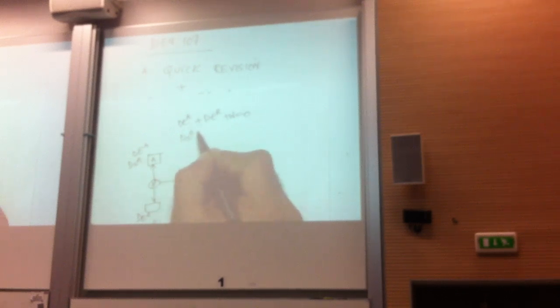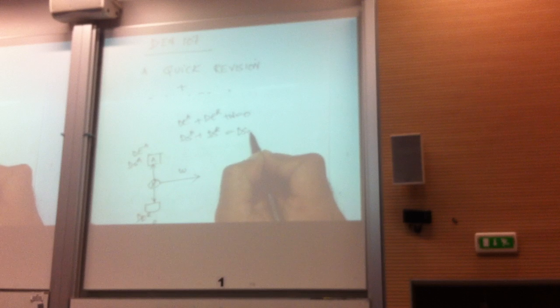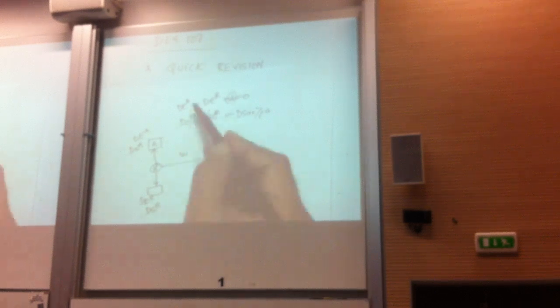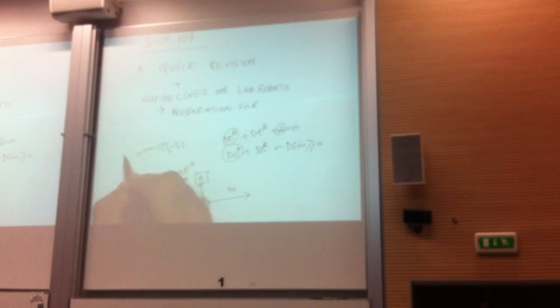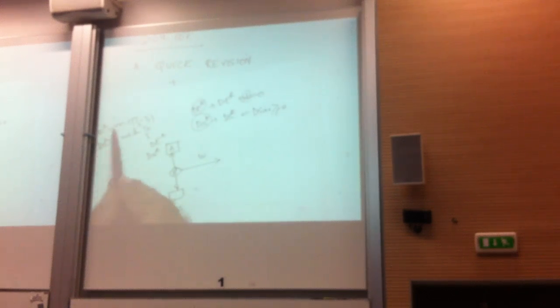dS of A plus dS of R is equal to dS_IRR, which should be greater than or equal to 0. Okay. Now the question is, if you are looking for work, in most cases you will be given a constitutive relation for dE_A and dS_A. If I remember right, you were given most of the time MC(T2 minus T1). This was your dE of A for that system, and your dS of A used to be MC ln(T2 over T1). You can correct me if I'm wrong.